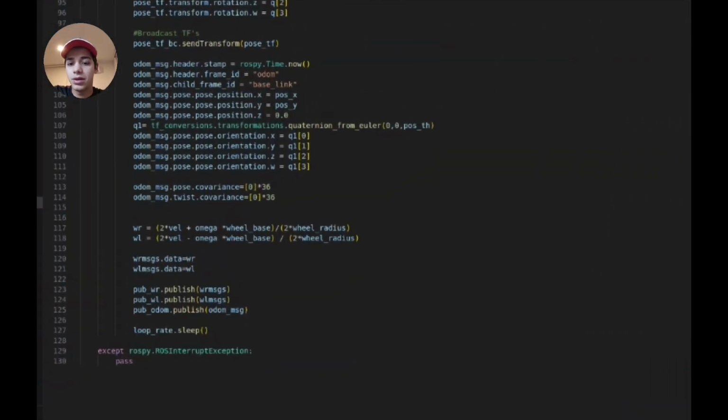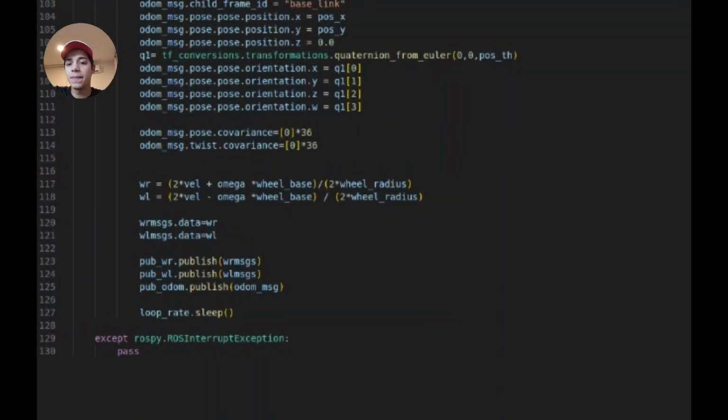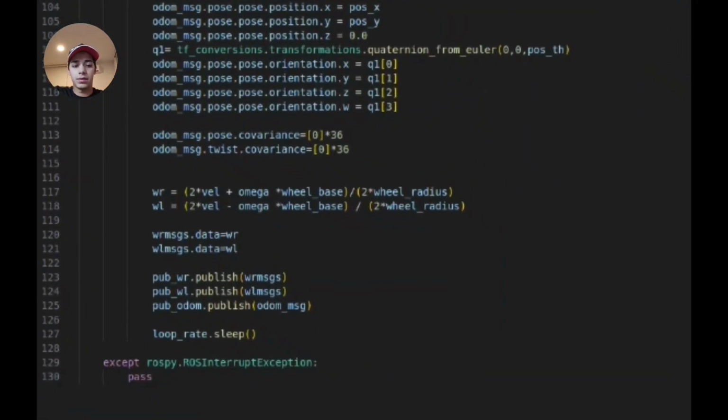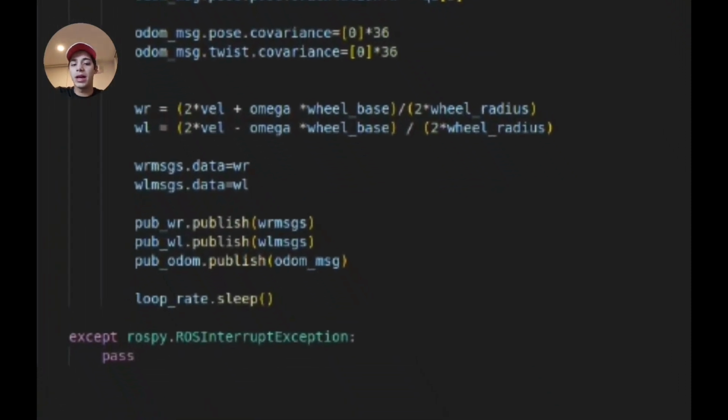And finally, here we're going to have the equations for our velocity commands. So here we're going to transform the high-level velocity commands into individual wheel speeds given by the variables from the right wheel and the left wheel, and we're going to calculate the angular velocities from each one of them. So this will ensure if the robot is going to go straight or if it's going to turn, so if one is going to go faster than the other.